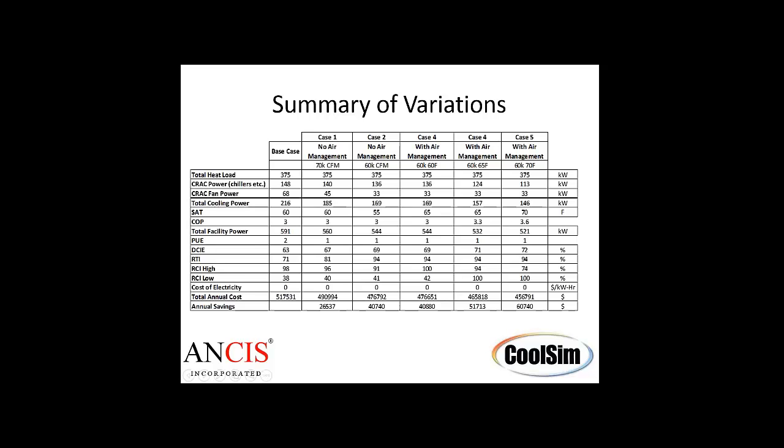And if I can get the system to operate that way, my coefficient of performance improved because I went up 10 degrees, so I got another 10% out of that. I went up 5 degrees, got another 10% out of that. 10 degrees will get you roughly 20%, so that feels just about right.